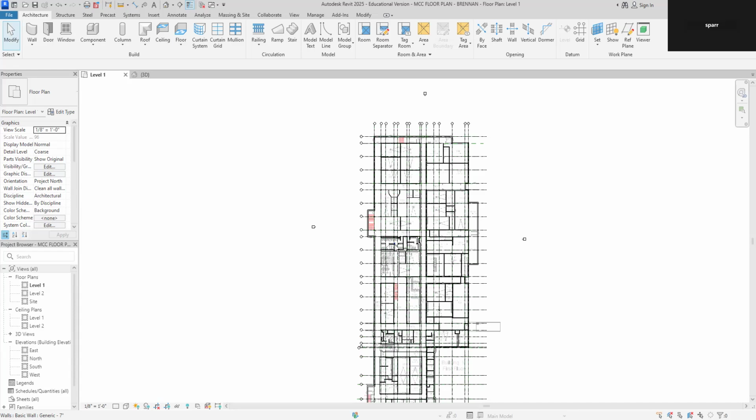Go back to your level one, let's take a look at that. Let's see what else we can take that. Oh, you know what that does? Yeah, we're ending it right here. Choose, get rid of those. To erase a wall, you can just press your escape key to end the wall, and then click on the wall, and then press your delete key, and that's easy. All right, so we're just working on that from last week, Silvana. Just continuing on.